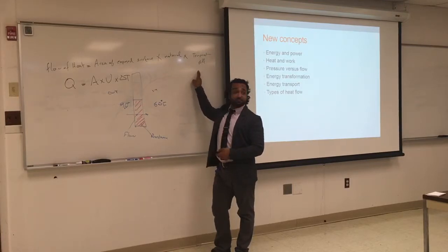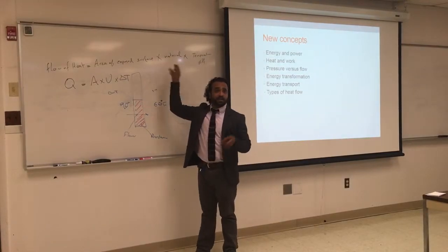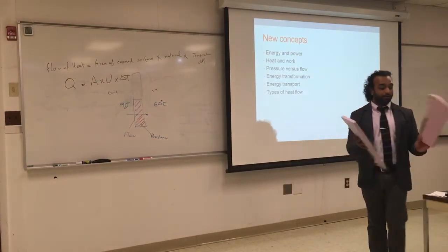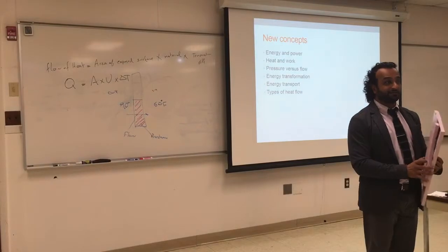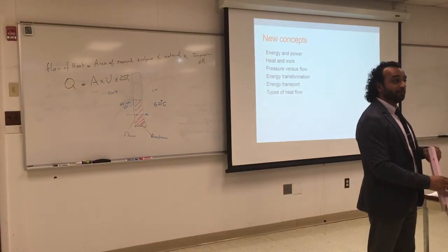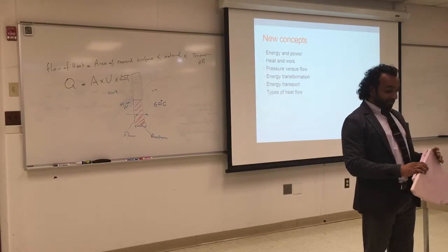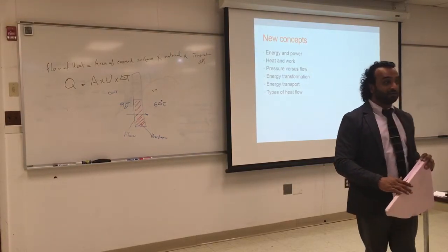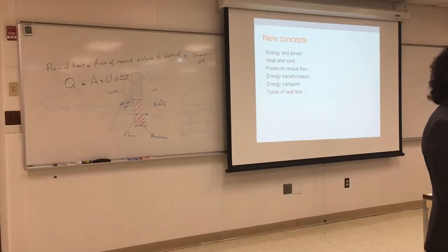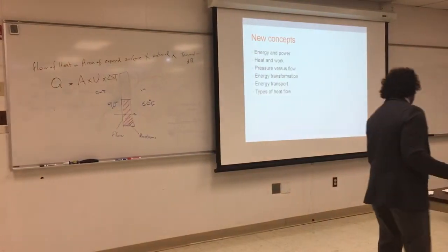You can go from 60 to 80. That's what you can control. Material is something we can control. You can add insulation, add more layers, and instead of R4, if they put them together, it's going to be 8. We can also get something thinner with more R value, more resistance. I'll show at some point that adding insulation to infinity is not going to help. There's a point when adding insulation won't help, so you cannot just keep adding it forever. We'll talk about that later.